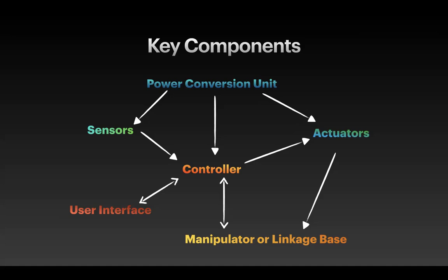And then there is another component which takes 15 volts, right? Your power supply or your battery is only 12 volts. So how are you providing a larger voltage? And then sometimes your controller or one of your sensors will be using 3.3 volts. So from 12 to 3.3. You need to do these conversions, right?